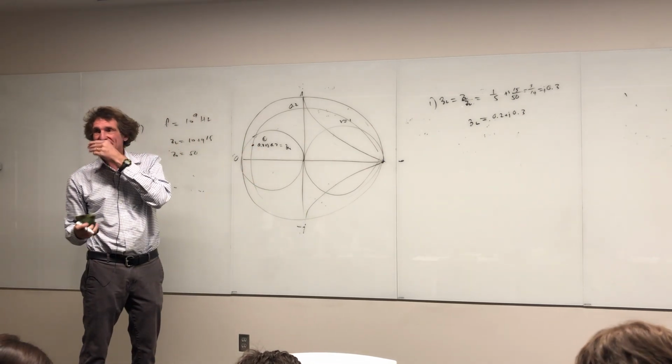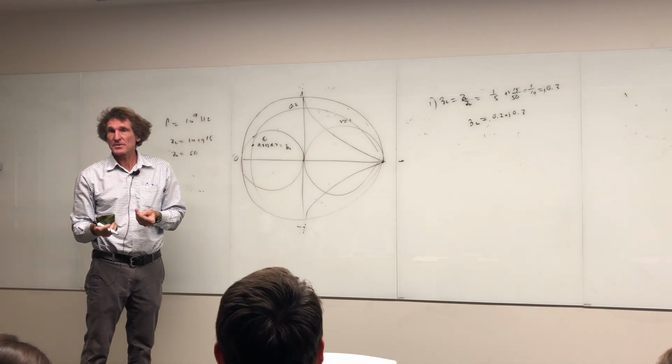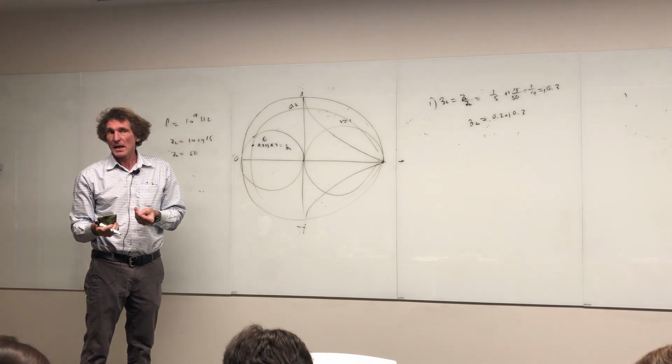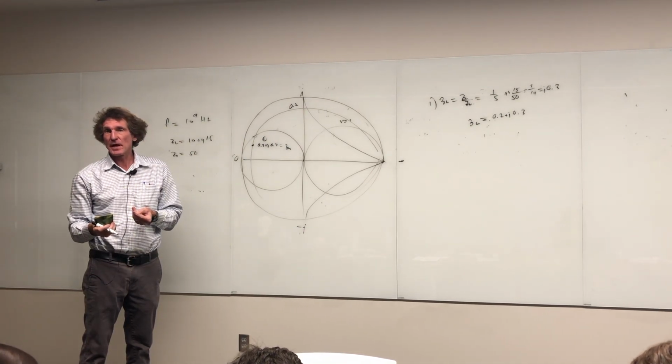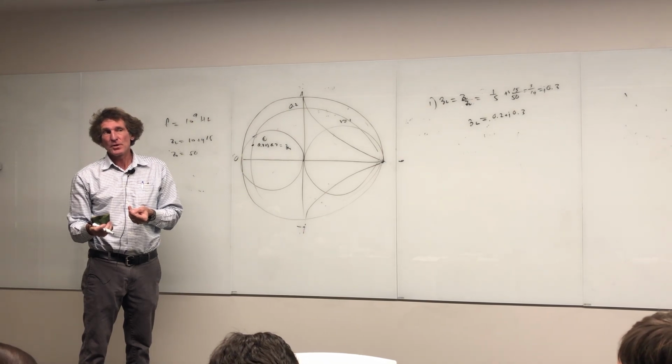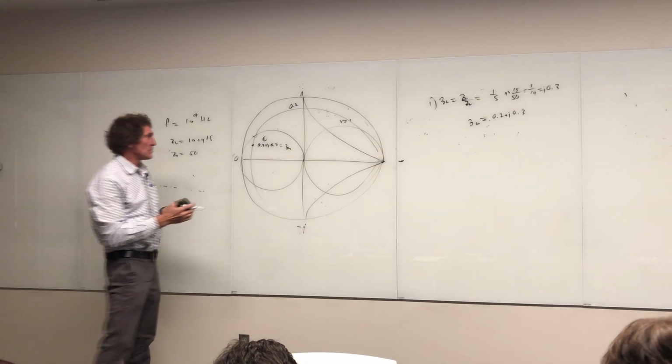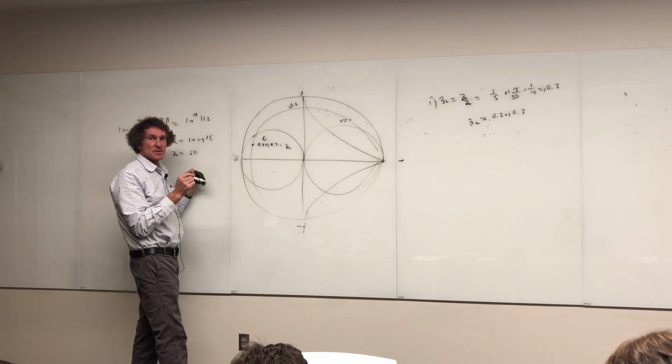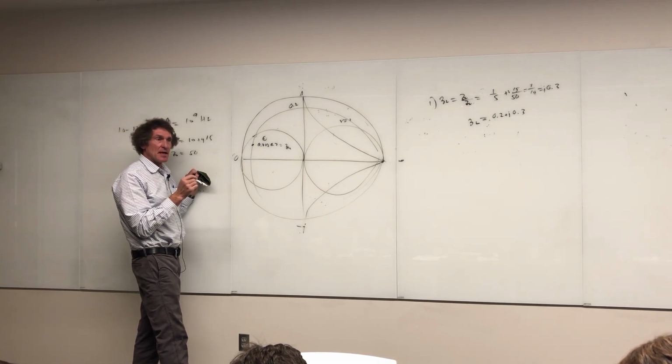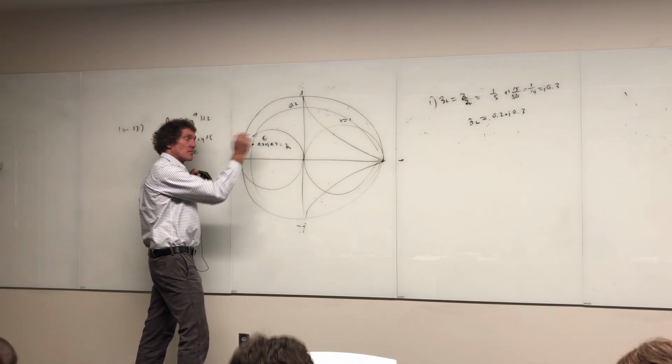Now, remember, that's an impedance. Can you all see it? And if you have Smith charts, can you locate that point? When you locate that point, you can see we can move two ways. Now, we're going to add impedance for this one. I didn't say that quite right last time. This one's inside the rotated circle. We add impedance because we're trying to get to the rim right there.